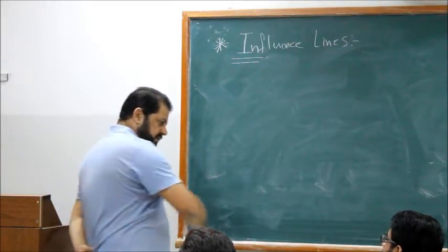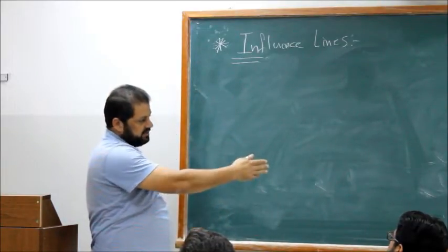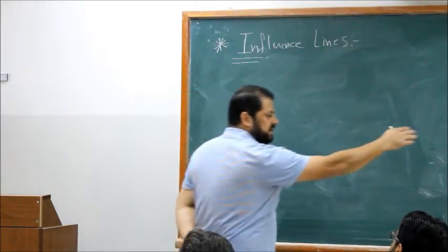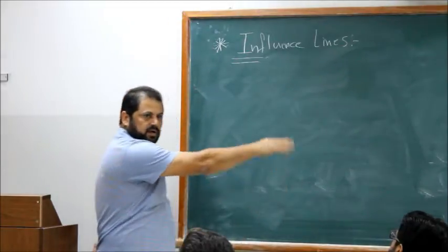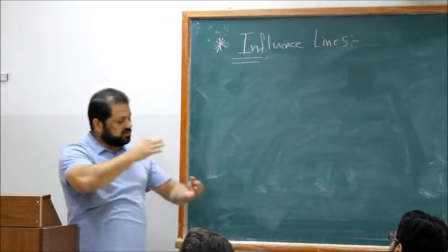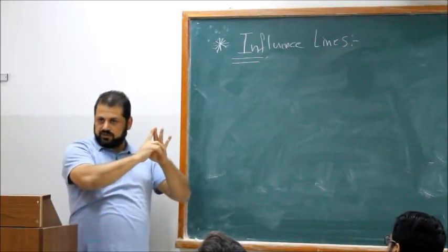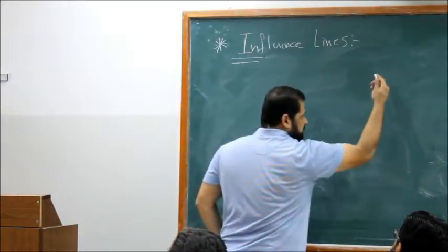If this unit load is moving on the beam, what's happening to the reaction? Let's say at the first support. What's happening when it's right there at the end support, and when it's in the middle? Good. So most of the time we are looking for reaction, shear, and moment. Reaction, shear, moment.